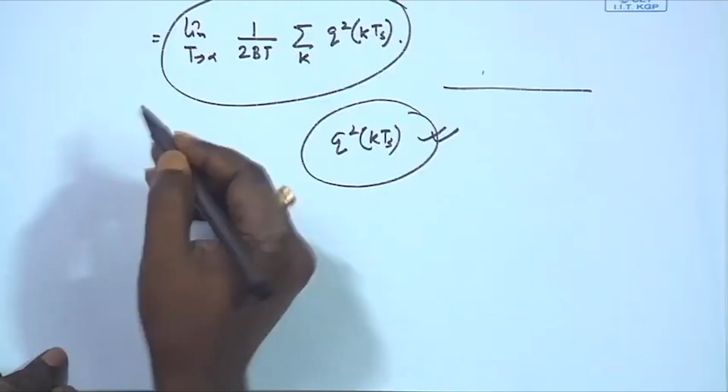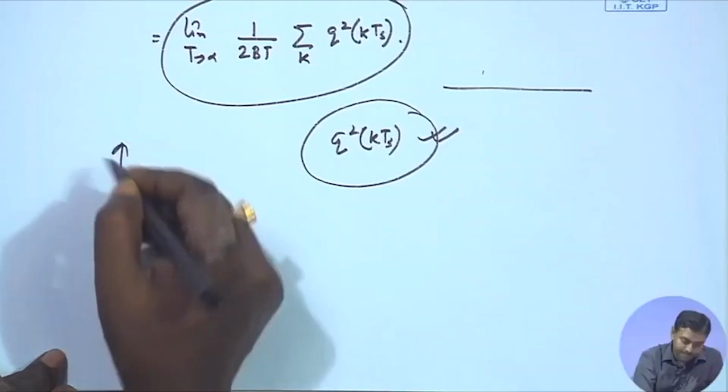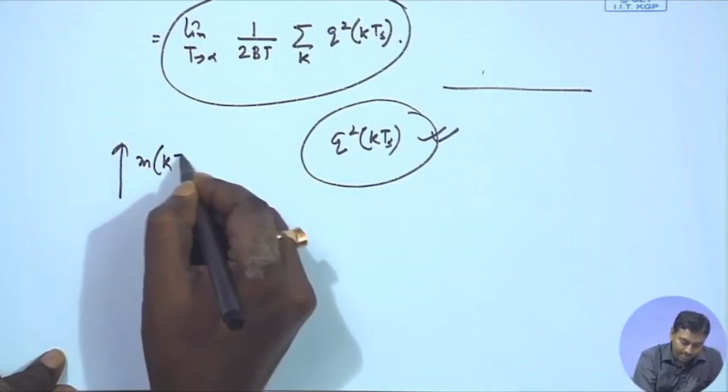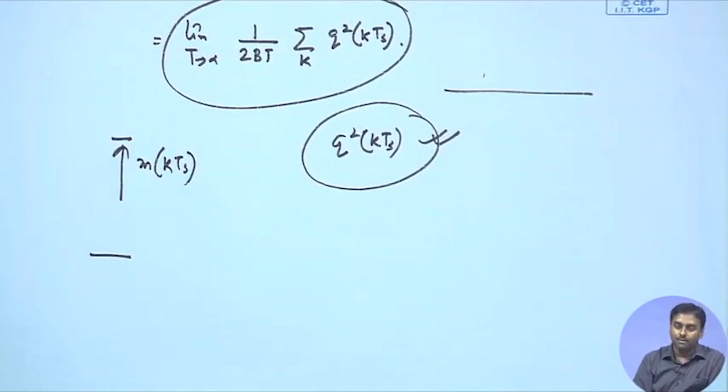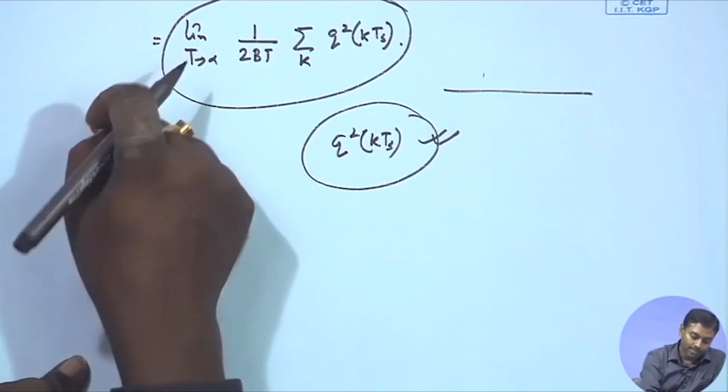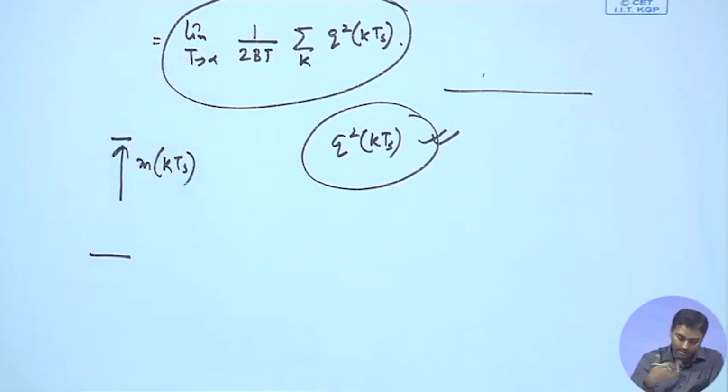Without proof, but people have tested that that is true always. So, if that is the case, the ensemble average will be the time average. So, we were trying to calculate the time average, that must be the ensemble average, and now we will make a further assumption that those samples, actual samples of m, means whenever we take m(kTs), those samples are uniformly falling between minus mp to plus mp. So, they are uniformly distributed.